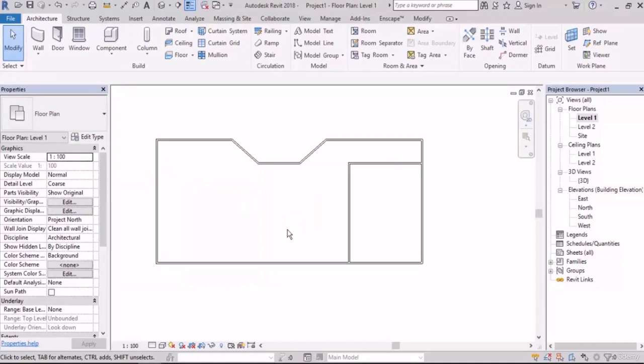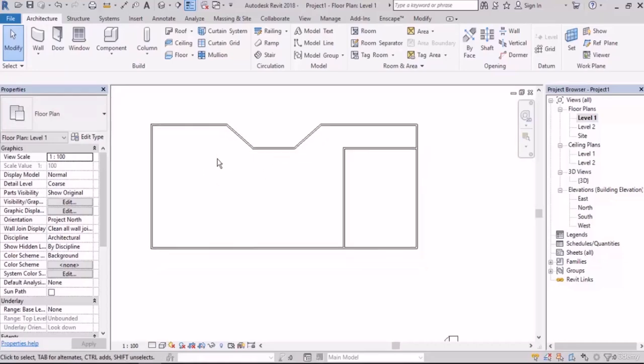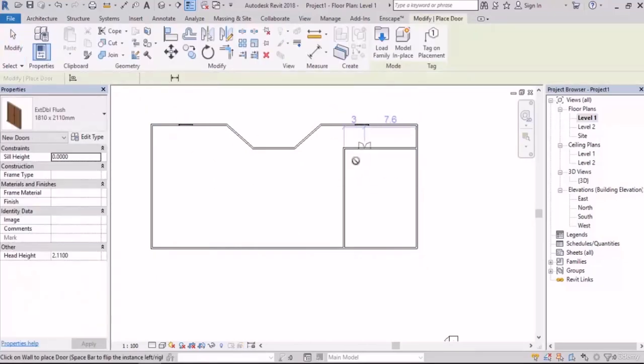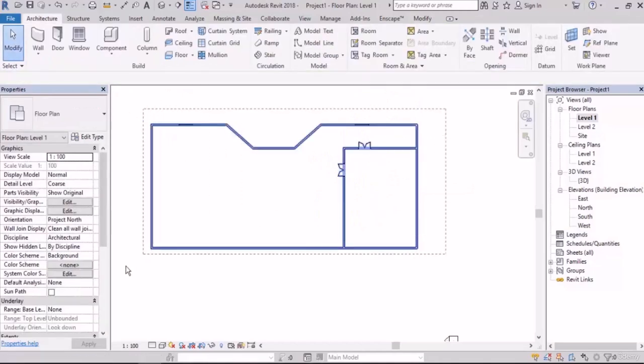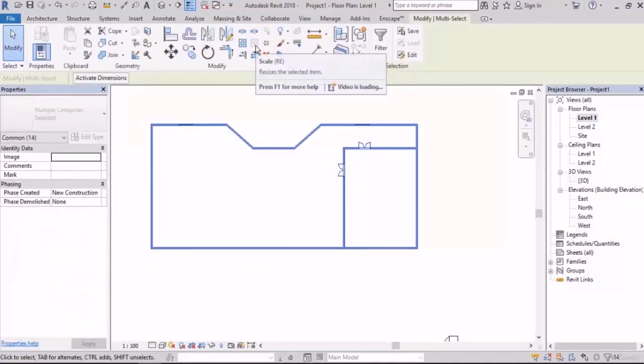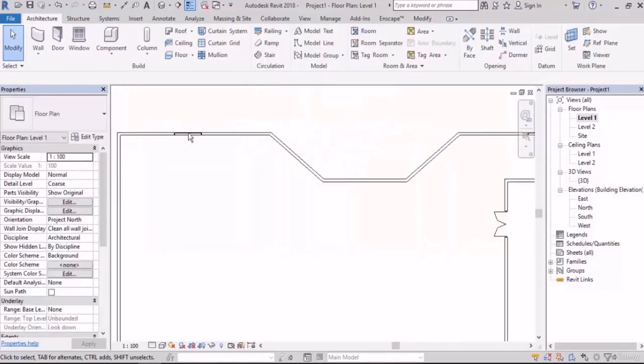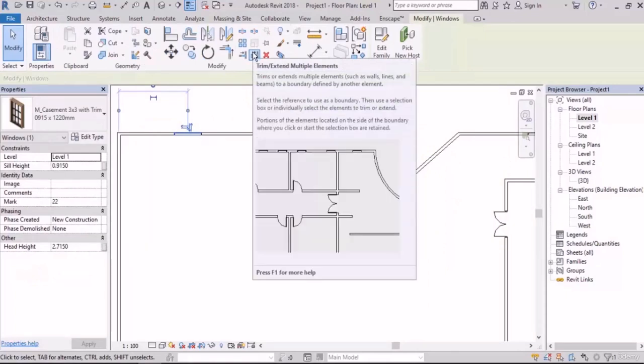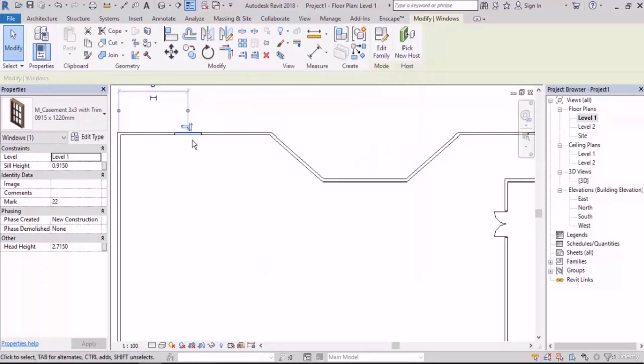Next tool is called scale. Well, I should say that scale is not used much in Revit because, for example, if you have a window in your project, or for example a door, when you choose these, then your scale will be inactivated. For example, the window can never be scaled. So I want you to change your mind about Revit from right now. See, it's not like Rhino and Max and other softwares. It cannot make the object small or big.